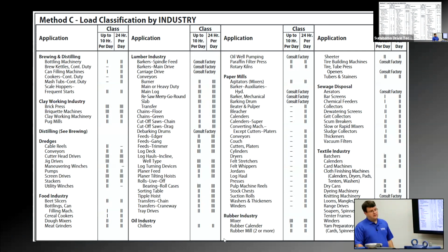There's other companies out there, SEMA, PTDA, that'll have recommendations for what type of loading. But if your application specifically isn't shown here, try to understand the most you can about the application. So know the speeds, know the weights that it's moving. If it's moving little tiny pebbles, then it's probably moderate to uniform. But if it's moving large boulders, it's definitely heavy. So you kind of, I hate to say learn as you go, but you understand what it's going through when you see what it's actually doing.